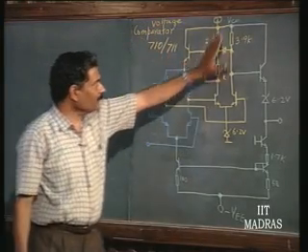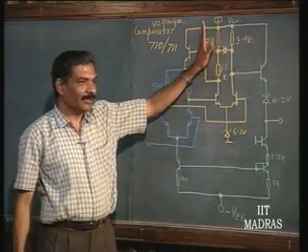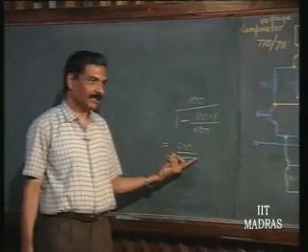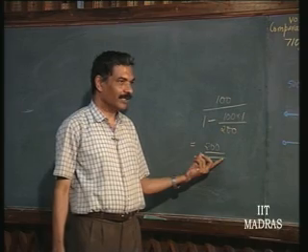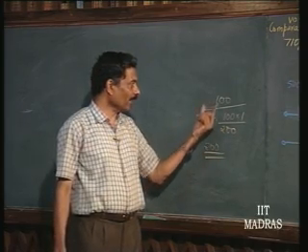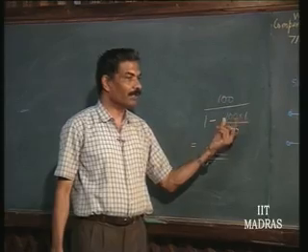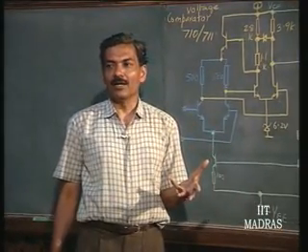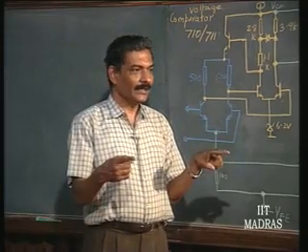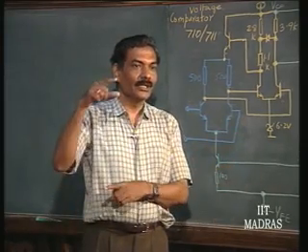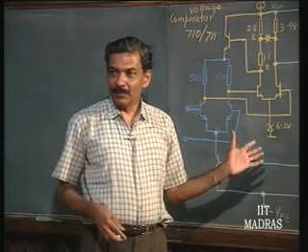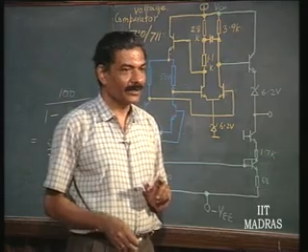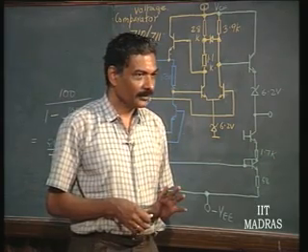I would like you to replace this structure by the equivalent circuit and prove that the gain is exactly behaving like this. If the initial gain is 100, okay, the final gain is 100 divided by 1 minus 100 into 1 over 200, and it becomes twice. This is another technique of converting differential output to single ended output by giving positive feedback, adopted primarily in comparator circuits where positive feedback is not going to matter, okay.